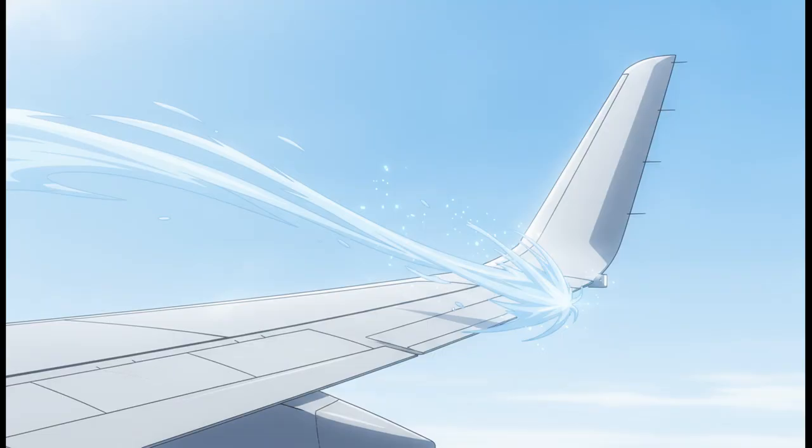To solve this massive drag problem, aerospace manufacturers use a couple of really clever methods to counteract the flow. They can taper the wingtips, which naturally reduces the pressure differential and simply smooths out the airflow. Or, and you've definitely seen these on commercial flights, they install vertical winglets. These winglets act as literal physical dams. They block the high-pressure air from curling over, preventing the vortex from ever forming in the first place.